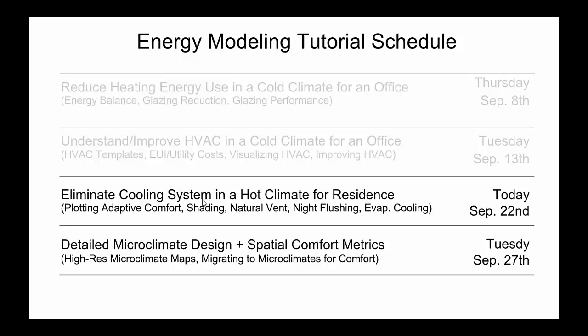We're going to go over a lot of passive strategies, how to apply those in Honeybee, and by the end we're going to get a sense of spatial comfort and get into multi-zone modeling. And then next Tuesday we're going to get really deep. We're going to start making high-resolution thermal comfort maps out of our energy simulations and go deep into the metrics we can use to quantify how comfortable our spaces are.